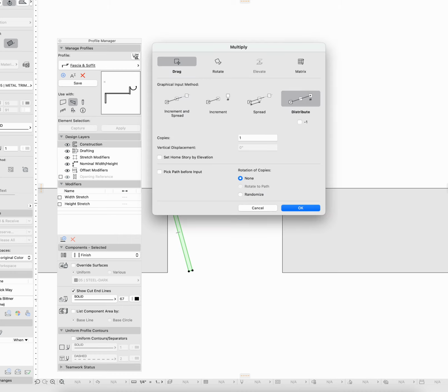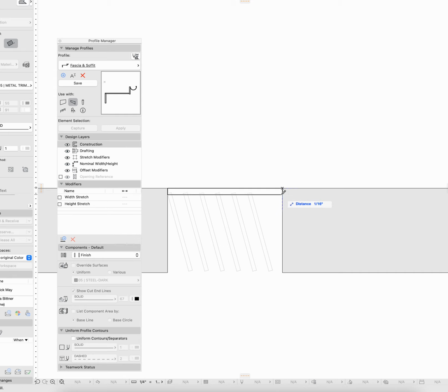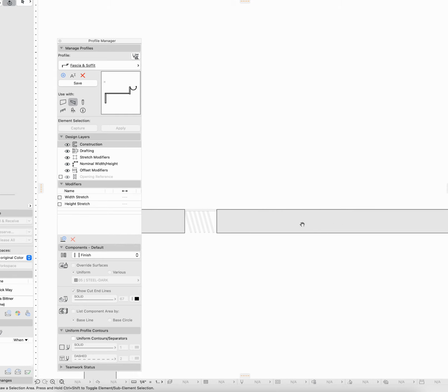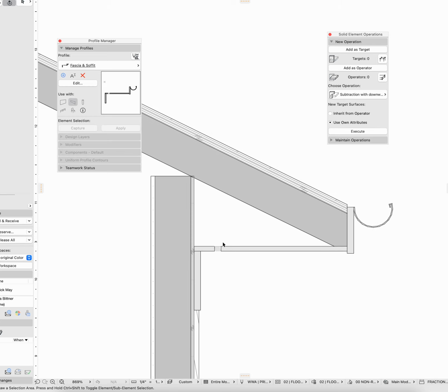and I can say that we're gonna have 5 fills from there to there. Right, so now I get my soffit vent. I maybe don't want to see up into there, so I'll put a cap on it just to clean it up in section. So now I have a soffit vent in there. Now I can say save and close. You can see that populates right there in the model.